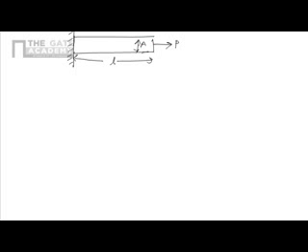So obviously the stress which has been imposed on the material is P upon A, assuming that area of cross section is uniform throughout the length. So it is A here, it is A here, it is A here also, and it is A here also. Everywhere it is A. Such a specimen is known as prismatic. What is prismatic? Prismatic is that specimen or that object whose area is constant throughout the length.